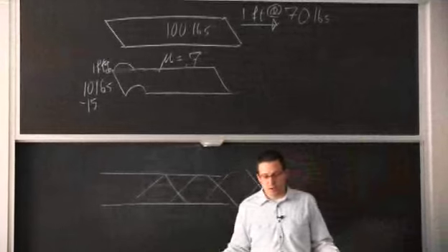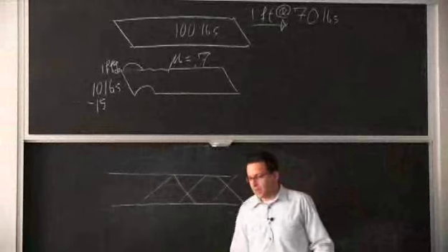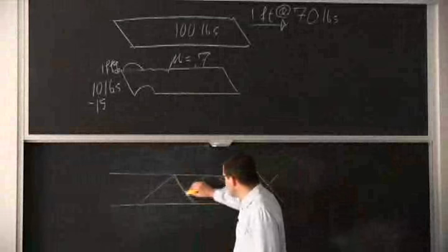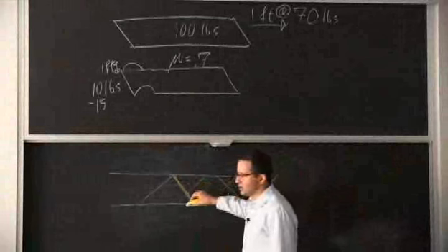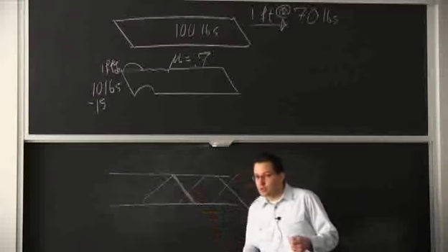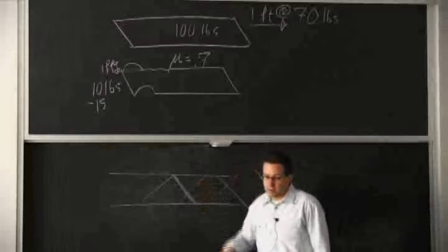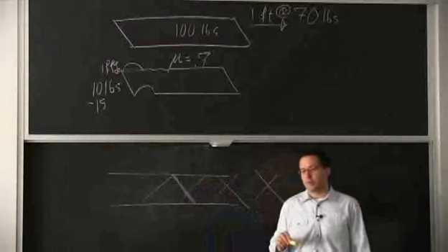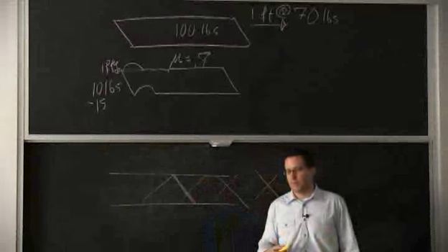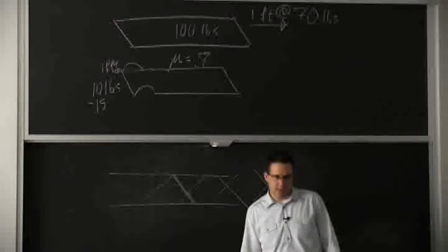So it's really the strain hardening that allows you to say, okay, yeah, I took some strain here, I changed shape, now I have even a little notch effect on the surface, but no, it's your turn to deform because now I'm stronger. That's what strain hardening really is.